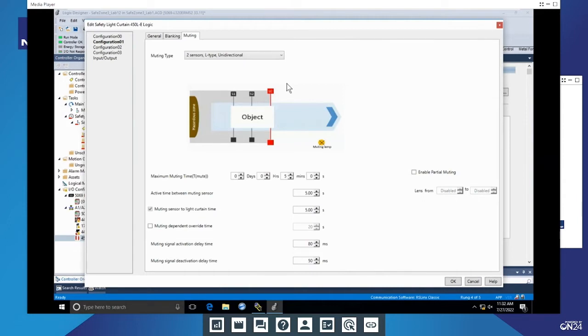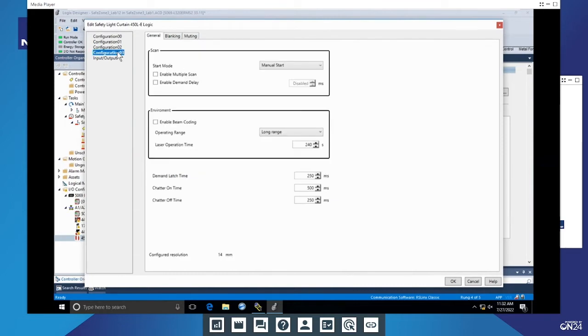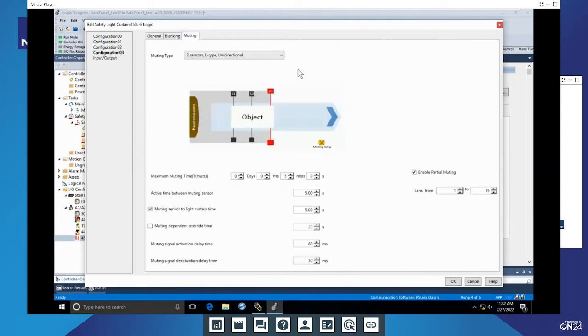Well, what I was going to say is, it's a typical example of sending empty pallets through a set of light curtains. If you're muting the light curtains, what's to stop someone from standing on the pallet and pretending that they're a product? Exactly. So for things like palletizers, this is a bit of a problem, because the way that muting needs to be set up in the standards is you need to make sure that the access to the hazardous area is still blocked off while muting is active. So, sending an empty pallet through, you're not exactly fulfilling that requirement.